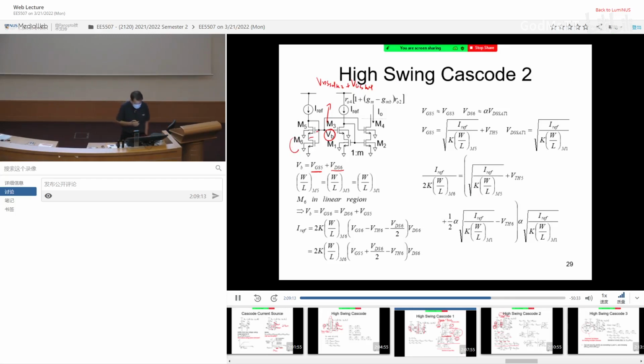Straightforward, right? Now, you make M5, M3, M1 the same. That gives you a very good benefit. Now your M5 will track M3. Which means when you form these two, your VB, one of the components given by VGS phi, already automatically tracks one of the components.